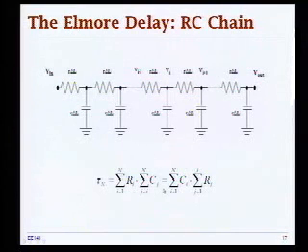So you can express this formula either as a sum of I going 1 through n over all the capacitances, and then you go upstream and calculate all the equivalent resistances, or you can sum up all the equivalent resistances and go downstream, calculating the sum of all the capacitances to the output.